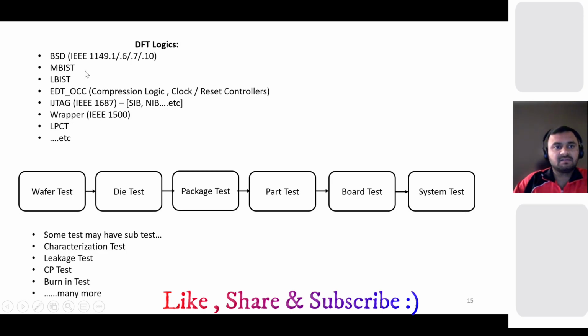The second one is memory built-in self test. If we have memory, we need built-in self test to test it, because we have different types of faults there. We'll discuss more later. Then we have logic BIST, which is needed for cases such as designing a chip for a car or for space, like rockets that go to space. You don't have any physical access, so you should have a built-in self test which can test itself. So there we have LBIST and all.